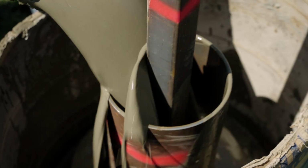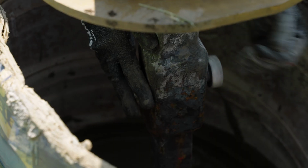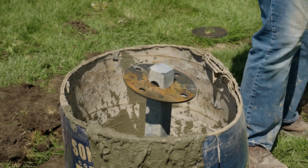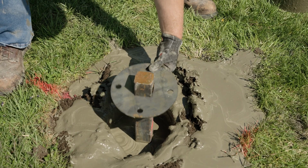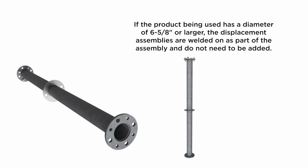on the grout column. Extension sections are added to obtain the required minimum overall length as shown on the project plans. Extension displacement plates are added at the connection of each extension section to maintain grout advancement and to centralize the pile shaft. If the product being used has a diameter of 6 5/8 inches or larger, the displacement assemblies are welded on as part of the assembly and do not need to be added.